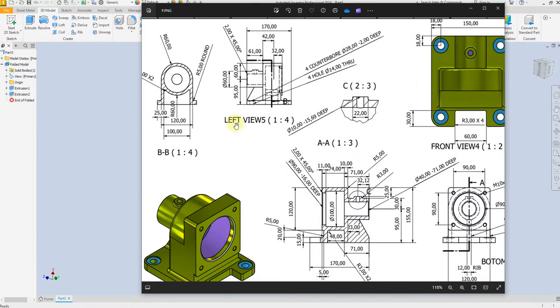Okay, now the second part, which is this one, we have the thickness 42 millimeter, and the width for this part we have here 120, from this line to this line, outer line 120. You see here 120, and the radius we have 60, which is diameter 120 millimeter.